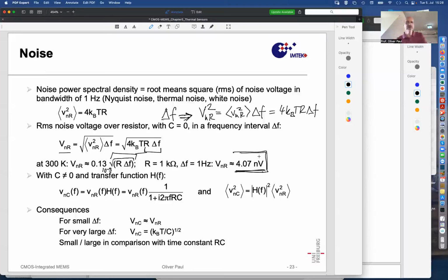So this is the resistor as standalone. If we have frequency here and we have V and R square, this is a constant curve. The fact that this is constant, that for every 1 hertz piece we have the same contribution, is what is called white noise, independent of frequency.